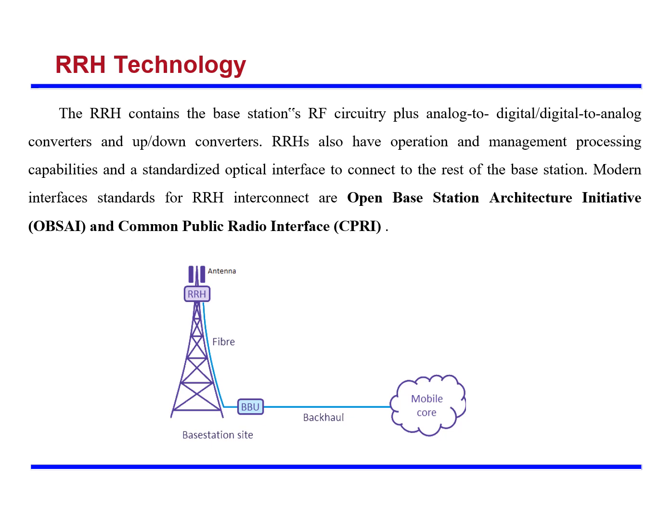RRH technology. The RRH contains the base station's RF circuitry plus analog to digital and digital to analog converters and up-down converters. RRHs also have operation and management processing capabilities, and a standardized optical interface to connect to the rest of the base station.